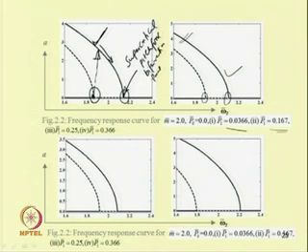To design the system, one should note that either it has to be operated at a frequency more than this omega 2 bar, equal to this supercritical pitchfork bifurcation point, or, if it is required, operated at a frequency less than the subcritical pitchfork bifurcation point. So, one has to take note of the initial conditions, and between the subcritical and supercritical pitchfork bifurcation points, the system will always vibrate at a non-trivial state. Similarly, one can plot the response for different values of P 1 bar, and